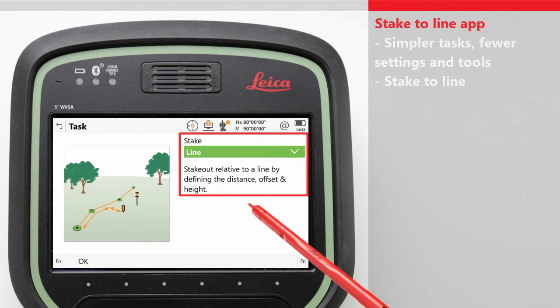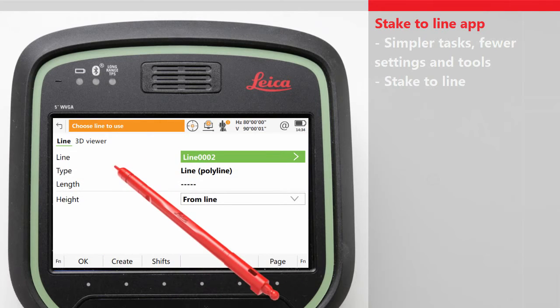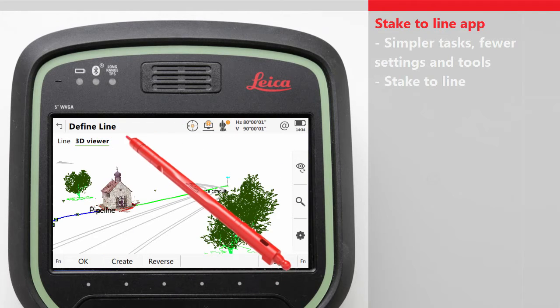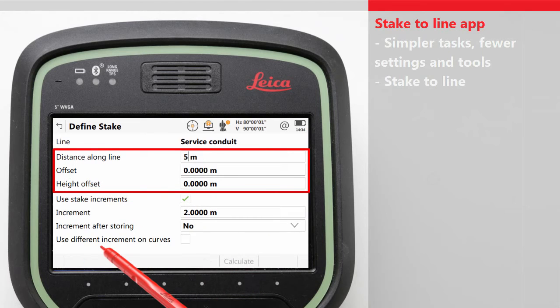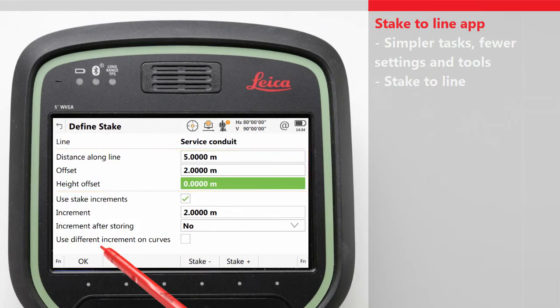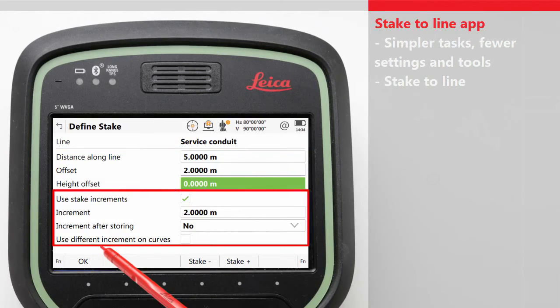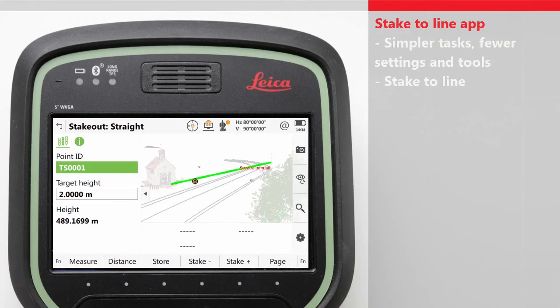Firstly, we need to choose the task. The Stake to Line task allows the line to be selected, the distance along the line, the offset from the line, and the height offset of the location to be staked. If needed, the distance along the line can be automatically incremented. And of course, the staking of the location. This is exactly the same as within the Stake Point app. Please do watch the How to Stake a Point video to learn more about the actual staking process.